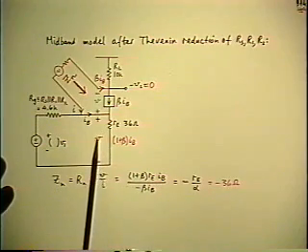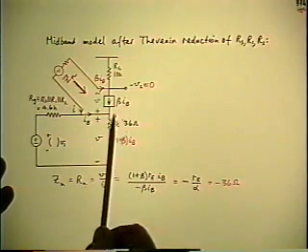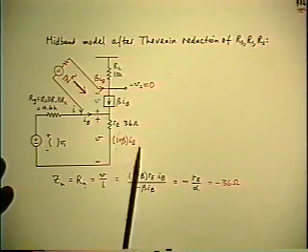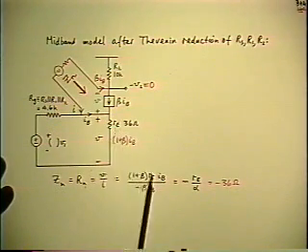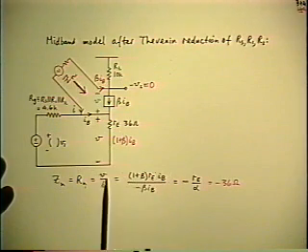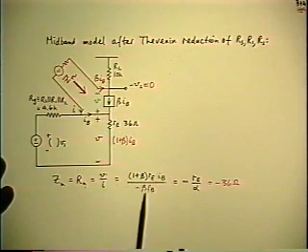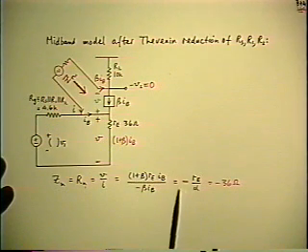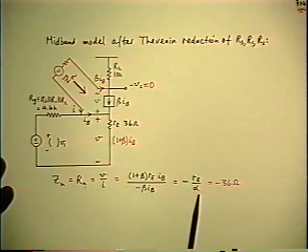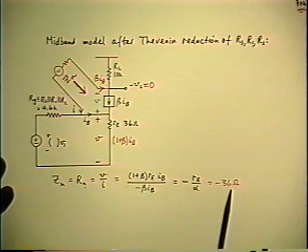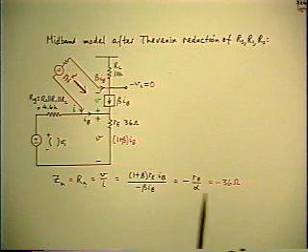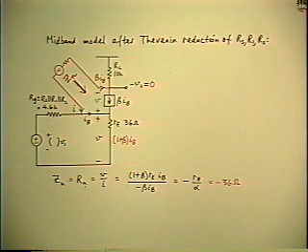So the green V equals the red V. But the red V is the drop across RE, which is the emitter current, 1 plus beta IB, times RE. So I substitute that for the V in the numerator. The IB cancels. 1 plus beta over beta is 1 over alpha, and the answer is minus RE over alpha, or minus 36 ohms. So that's a very short, simple process, certainly compared to the ZD calculation.